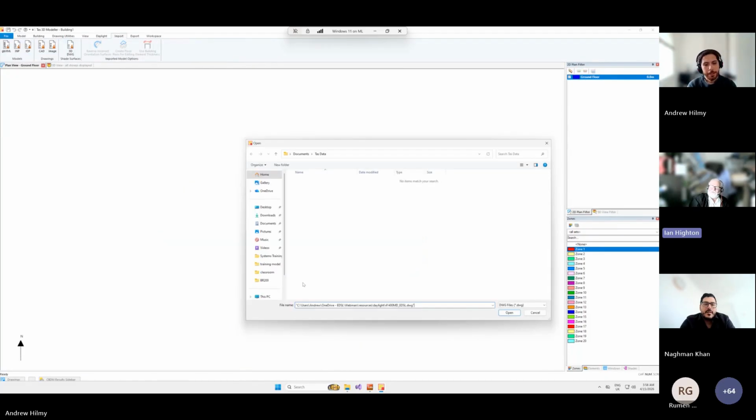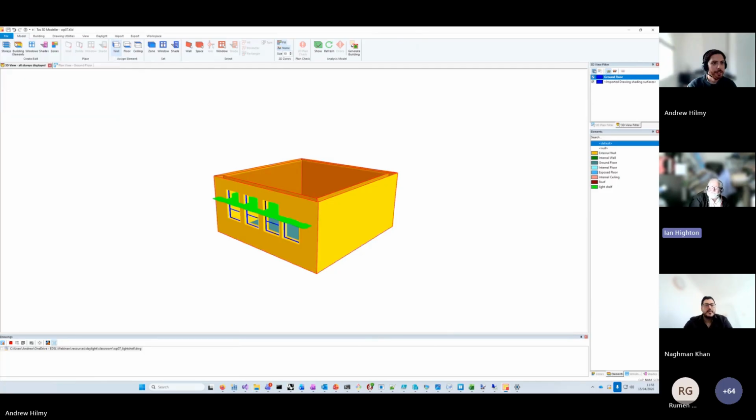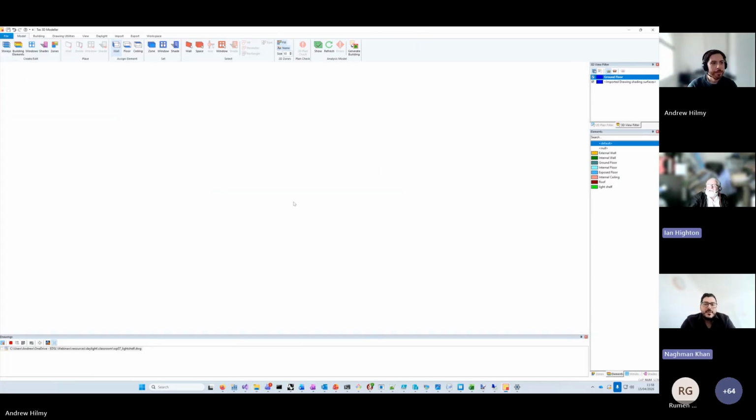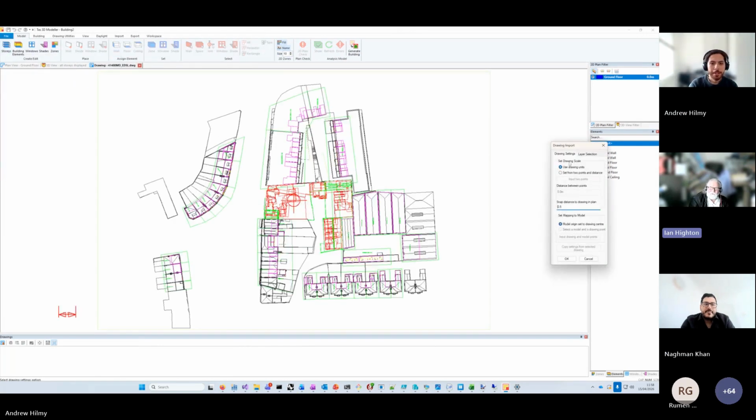Then we put all of that into the software, ran the daylight calculations, got the lux values, and went, yep, that looks good. We're happy. We're within a few percent. Obviously, we had to make assumptions about the transmission of that roof light, so there was a bit of give and take, but we got the right distribution, which was the most critical thing from our point of view.